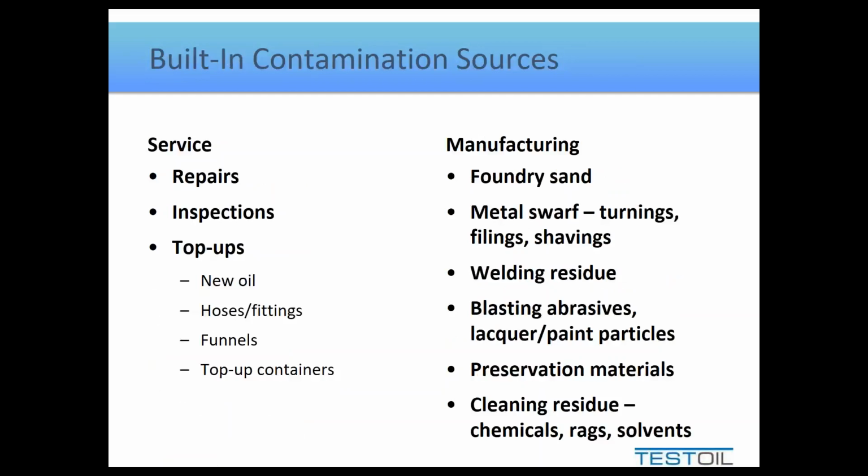Last but not least, we know that some particulate is there before we even put the lubricant in. Sometimes the contamination is there because we try to do something good to the system. So that's why I start the first column with service. Anytime something is being serviced, if it's being opened up, it's being exposed, or at least given the potential to get further contaminated. So when we think about some of the activities that we do, are we doing these activities in a way that tries to prevent the system from becoming contaminated?